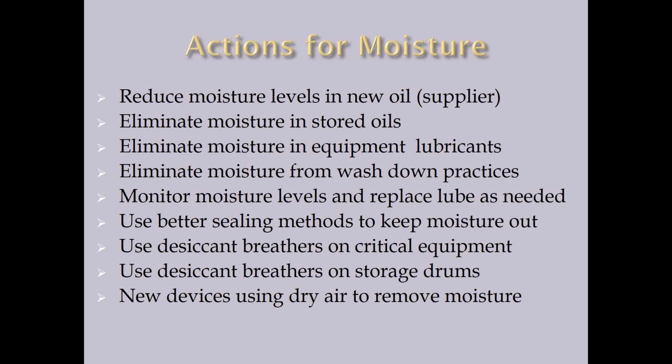Eliminate the moisture in your stored oils. Where are you storing your drums? Where are you storing your buckets? What kind of containers are you using to take the oil around to your plant? All these different components and all these different methods you have at your plant, you can get moisture in your oils before they even get to the equipment.